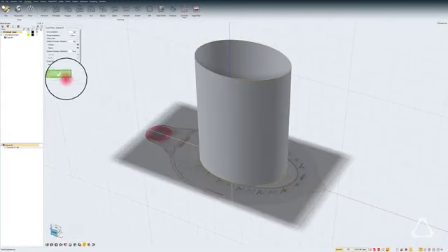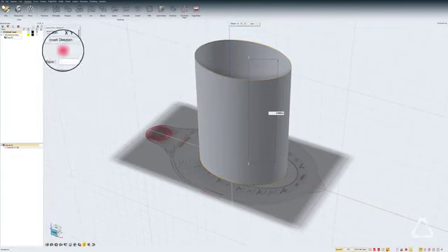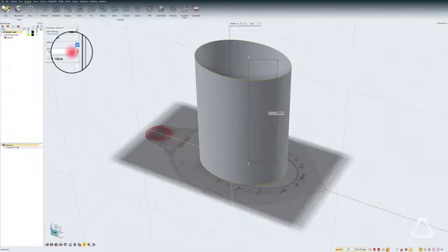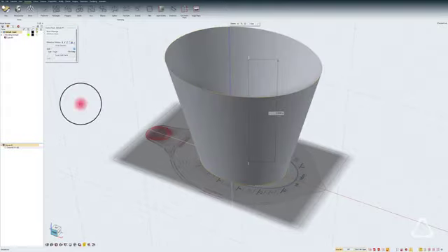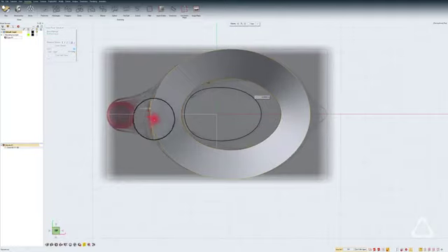So with shaded mode, you can double click on the extrude and make sure that the draft angle is enabled. We want to give a draft of -13 degrees, and this is something you can try out in the top view, and you can see that with the 13 degrees it's matching the edge of the image we have underneath. So you want to try whether it's 13 or 13.5, it doesn't matter. The point is that there is a draft that's required to meet this shape.